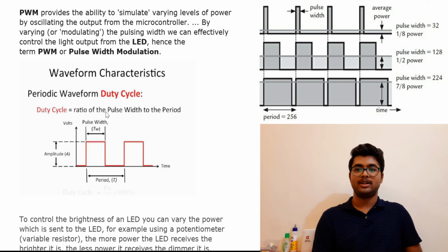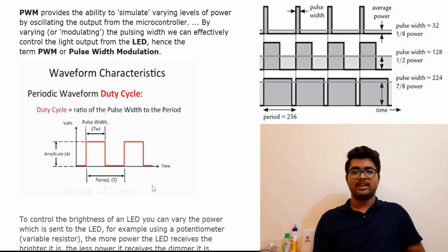The more the pulse width, the more the duty cycle, and thereby the more the voltage that the LED bulb will receive. So by seeing this parameter, we can guess the voltage that is supplied to our appliances. Now let us note another concept in this graph. These are the two levels. This level is the high level and this level is the low level.